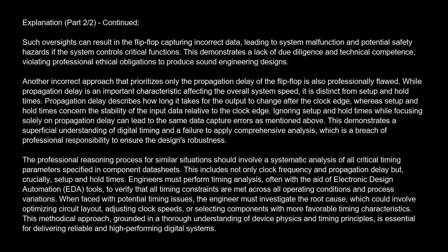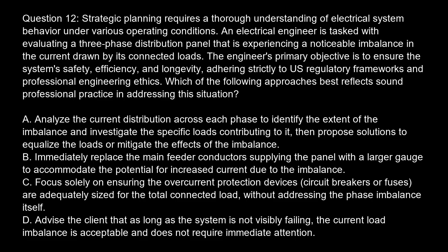When faced with potential timing issues, the engineer must investigate the root cause, which could involve optimizing circuit layout, adjusting clock speeds, or selecting components with more favorable timing characteristics. This methodical approach, grounded in a thorough understanding of device physics and timing principles, is essential for delivering reliable and high-performing digital systems.